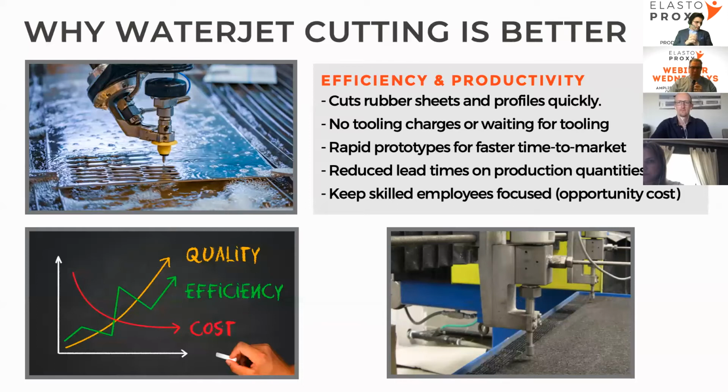The efficiency and the productivity. So I think one of the biggest things, if you compare it to die cutting, we get compared a lot to die cutting. So yes, die cutting, large volumes, absolutely yes. Go ahead and do die cutting. There is going to be a tooling charge for die cuts. However, if you have high volumes, and I'm talking thousands, not tens of thousands, it's worth going towards die cutting parts.